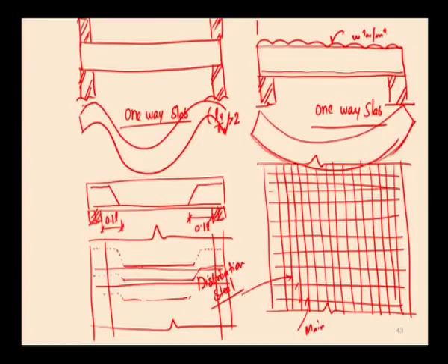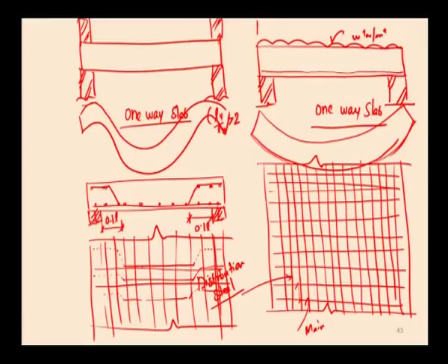keep this main reinforcement in one direction, that is, in a one way slab, there is reinforcement which is provided in the perpendicular direction. That reinforcement is called distribution reinforcement. So, in order to resist the partial restraint over the support, the IS code says that only 50% is more than enough to resist the partial restraint which is developed over the support. That 50% of the reinforcement has to be provided over the support.